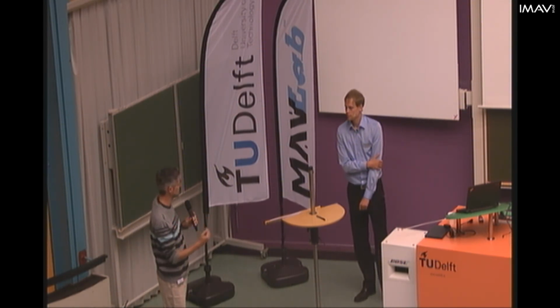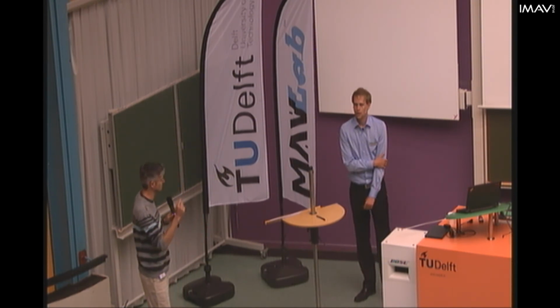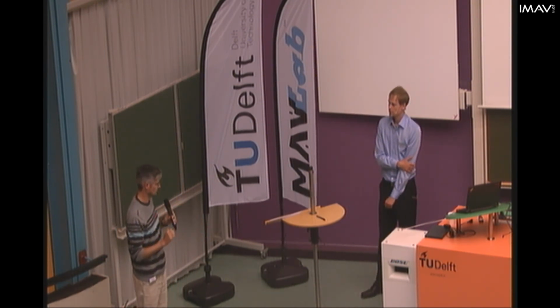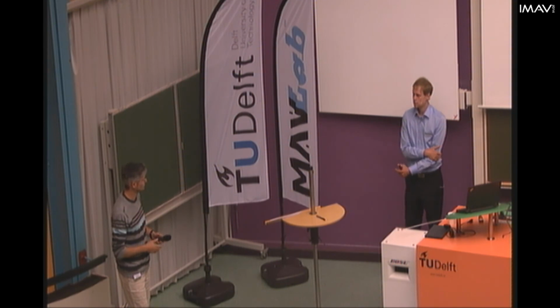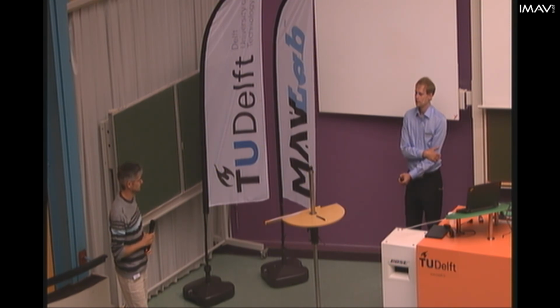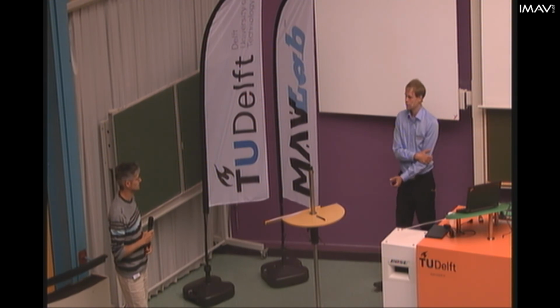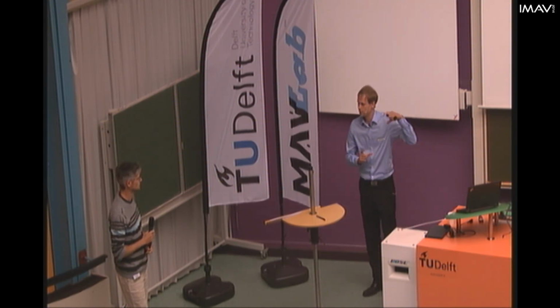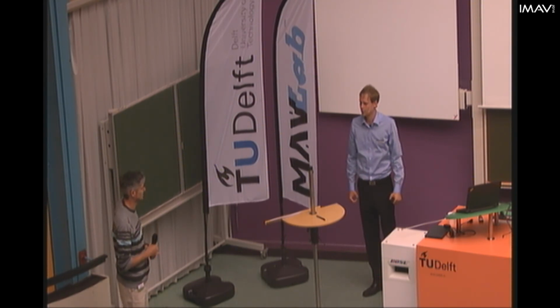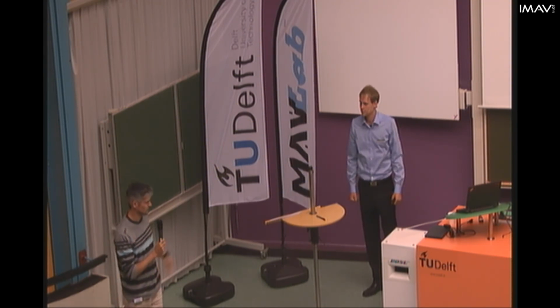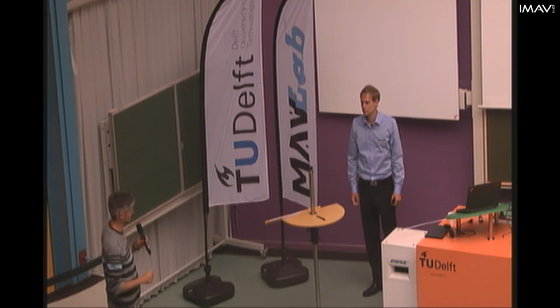And did you see these effects in your measurements when you were trying a differential with the wing completely tilted up? Probably we saw them. We didn't really put our focus on them. We just inverted it, and then we were fine with that. But we only investigated stationary effects, and usually in real flight we have a pretty huge tail, so maybe this would not affect so much, but in stationary effects we should have recorded it. Okay, so that's negligible against the roll. Right.